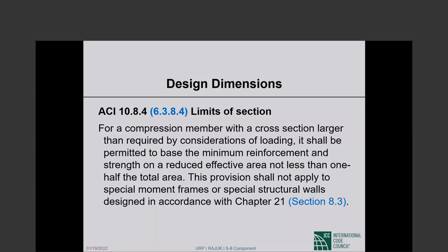As you go up, two things change. At the very base, where the loads are the highest, you use a very high compressive strength of the concrete. You may go with, I don't know, 11, 12 KSI. And a very high reinforcement percentage, something like 3 or even 4%. Then you taper the reinforcement off. As you go up and the load decreases, you decrease the reinforcement. By the time you have hit 1%, you switch to a lower concrete strength and a higher reinforcement percentage. And then you do the same thing.